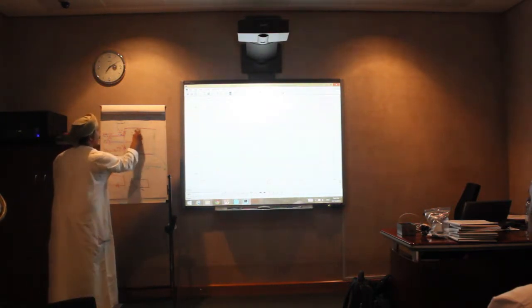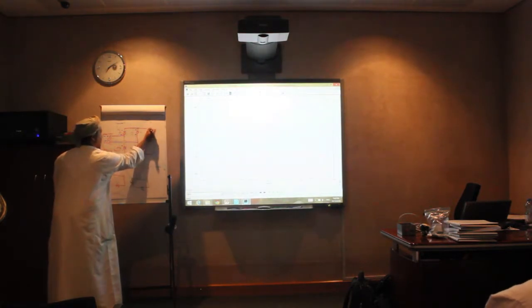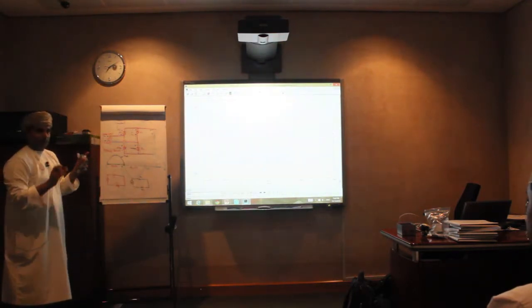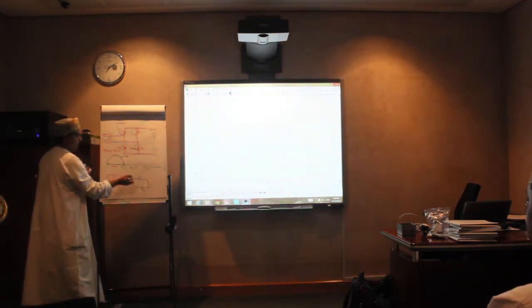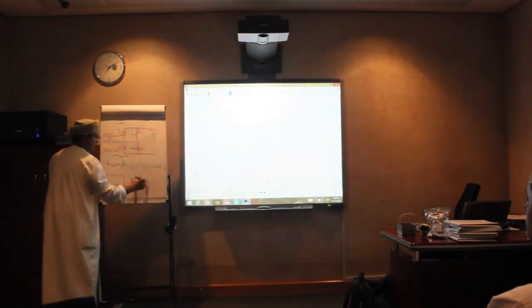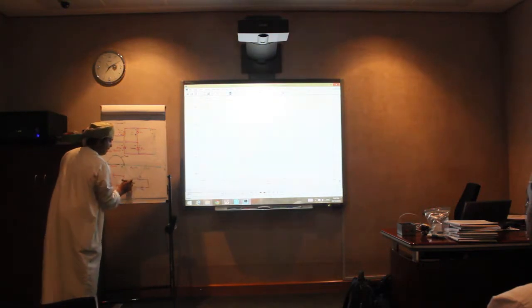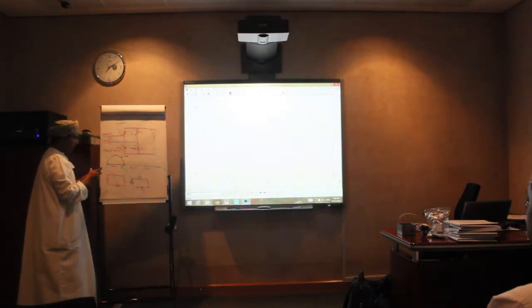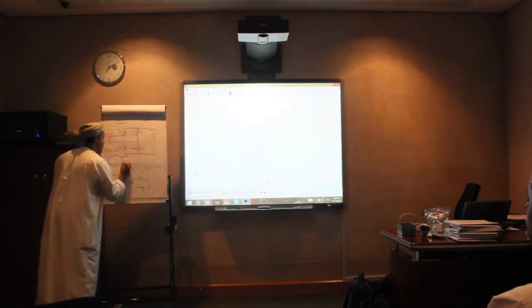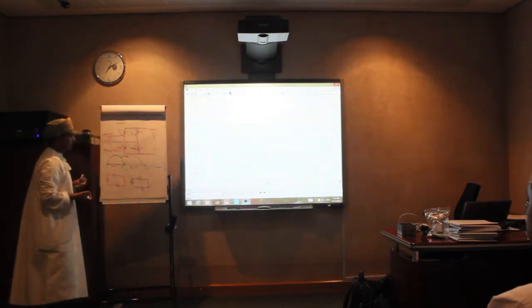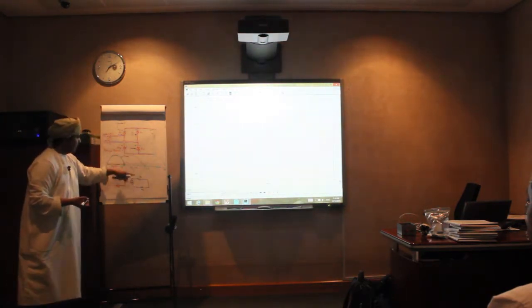See that loop? In both loops, the current is entering from this side, right? So both of them are in the same polarity, in both half cycles. So what is the voltage across that one during the second half cycle? Positive. So that means it is equal to the source. Therefore, in the second half cycle, across that resistance, we will get that envelope up, the opposite of this one.